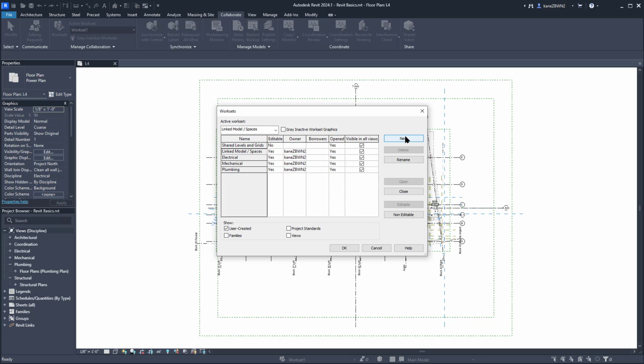If your company splits the M, E, and P into separate files, and you'll have multiple people in the same discipline working on a file, you might define worksets more granularly. So for electrical, that could be distribution for your panels, power for your receptacles and things, and lighting. I've also seen people define worksets by the building floor or section, or some combination of that and discipline, or an entirely different scheme altogether. Some prefer to not even use worksets. It all just goes into workset 1 and that's it. The right configuration for you will depend on your situation.